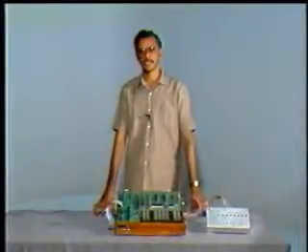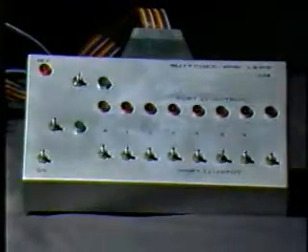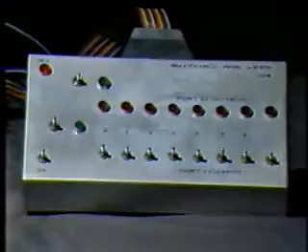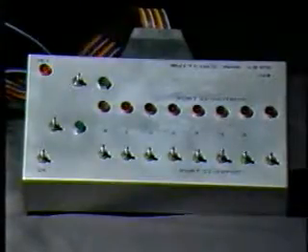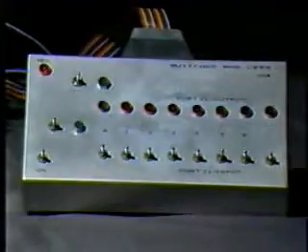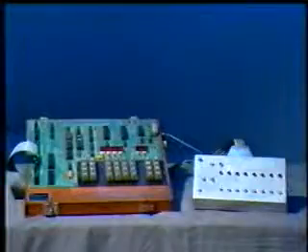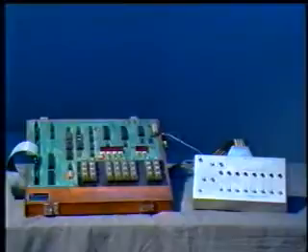The external devices connected are LEDs and switches. The 8 switches are connected to port A and the 8 red LEDs are connected to port B. The port A is operated in input mode and the port B is operated in output mode. The device is operated under mode 0. A program is executed which will switch on the LEDs one by one in sequence.